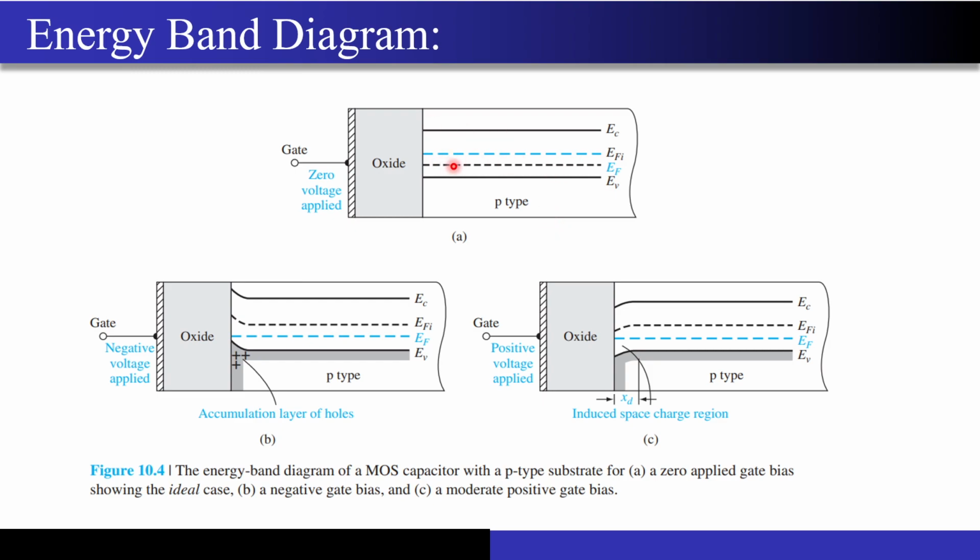The Fermi level that you can see over here is lying very close to your valence band, because this is your p-type semiconductor, right? And now you have a metal over here. It just has this flat line which represents the Fermi level, correct? It does not have the energy band gap that we see in semiconductors, or the large band gap that we see in the oxide case. Now what actually happens?